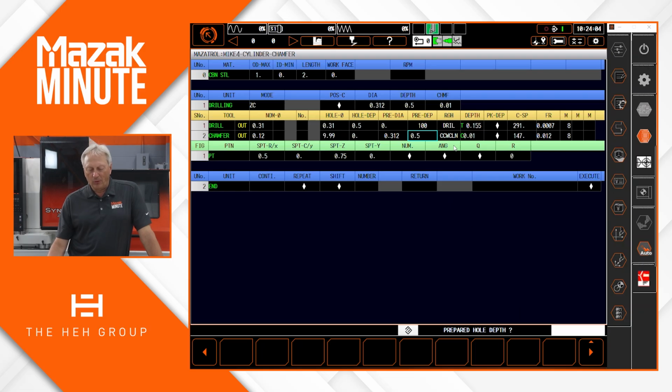And then when I come to the roughness, this is where you see the standard clockwise cylinder, counterclockwise cylinder. These two here are going to give me that consistent chamfer. I enter the depth of the chamfer under the depth, and I give it my speeds and feeds. When I come down to my figure pattern, we're going to come over here. I'm going to select point.